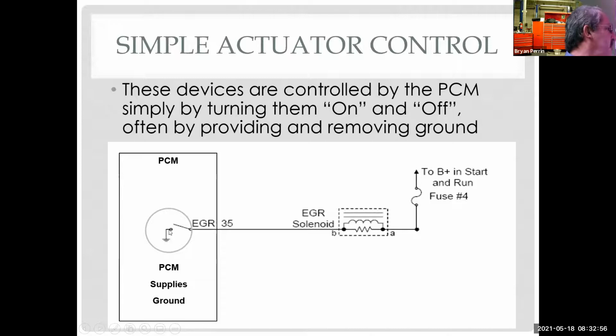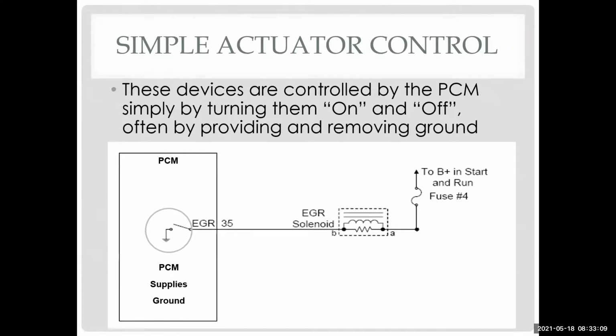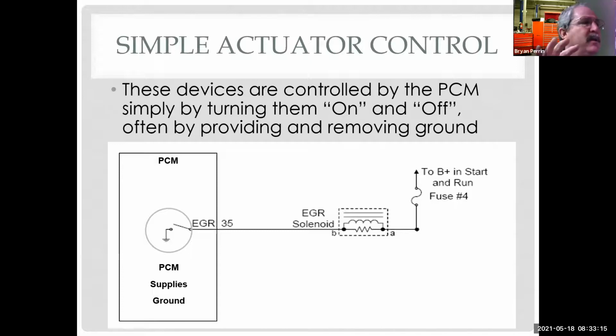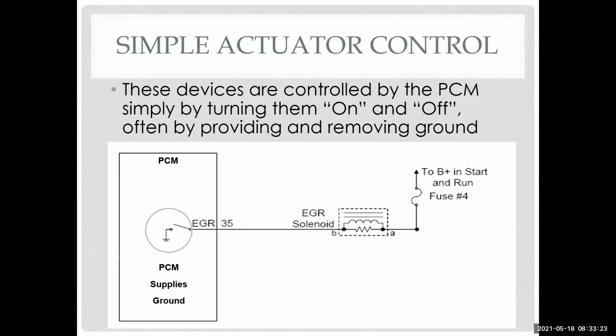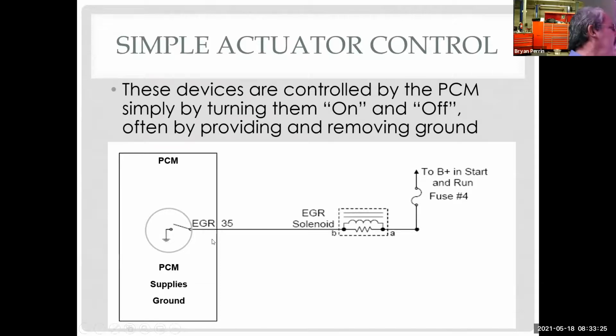When this switch closes, what's going to happen to my meter reading? If I have system voltage with it open, what's it going to do when it closes? The solenoid will work. EGR solenoid. Yeah, well, it's not about the EGR. What is the voltage going to be at pin 35 when the switch closes? It should be 0, right? So I'm going to go between 12 volts, or system voltage, when I'm off, to 0 volts when I'm on, because it's ground side controlled.